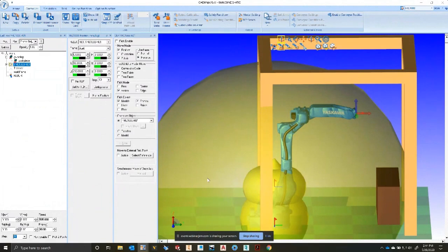If your robot was too far away, you would know. This is the workpiece. It would be outside the bubble, and there's no way the robot would reach it. So anything inside the bubble and outside the inner envelope. So here's our outer envelope and our inner envelope. Anything between there, the robot should be able to reach to.